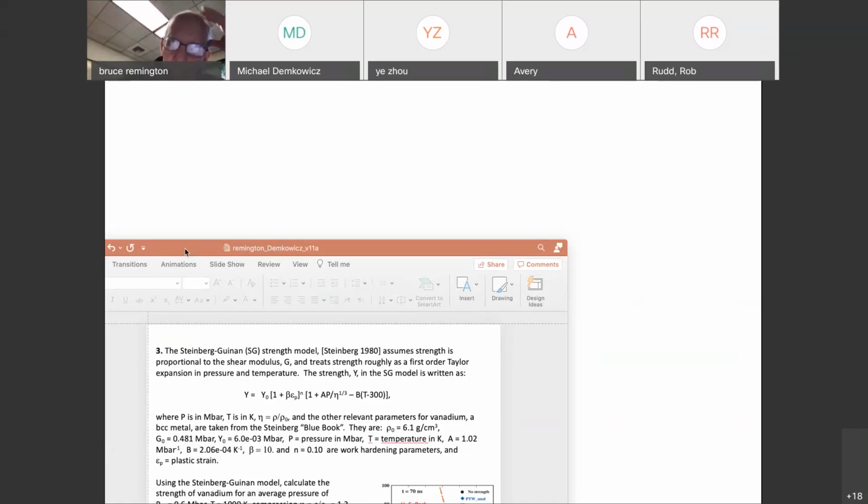And, at lower pressures, the compression is essentially unity, and you just get kind of the linear pressure dependence. So at that point, it's not too sensitive to the density. But, as you go up in pressure and compression, it does depend on both of them. And so you do need to use the equation of state to get at the shear modulus in those conditions.